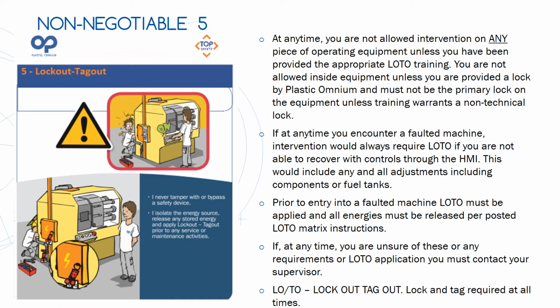Non-negotiable 5. At any time, you are not allowed intervention on any piece of operating equipment unless you have been provided the appropriate lockout-tagout training. You are not allowed inside equipment unless you are provided a lock by Plastic Omnium. This lock must not be the primary lock on the equipment unless training warrants a non-technical lock.